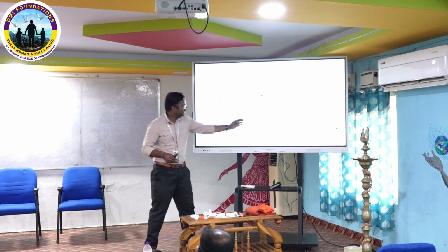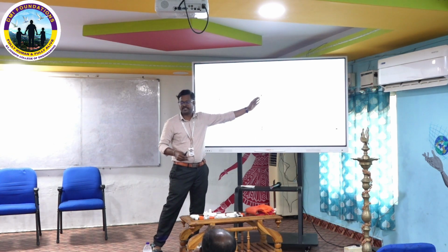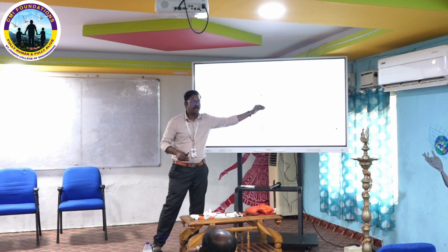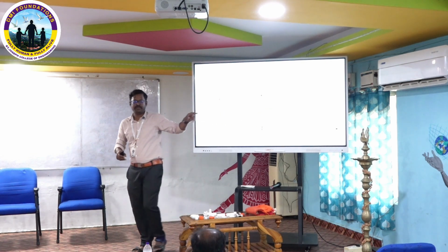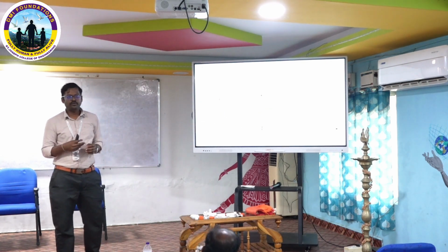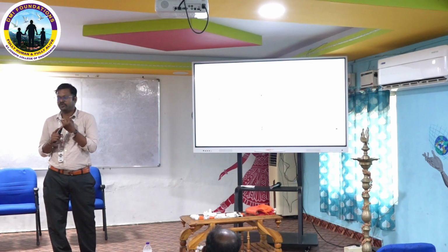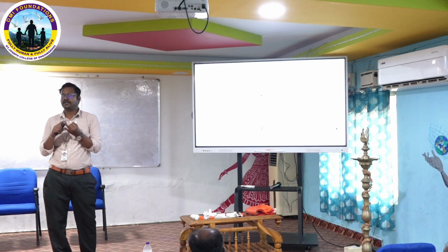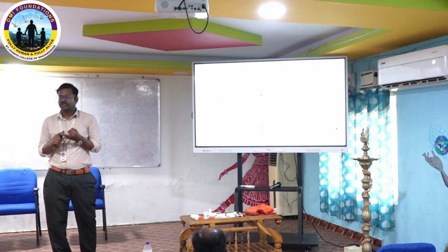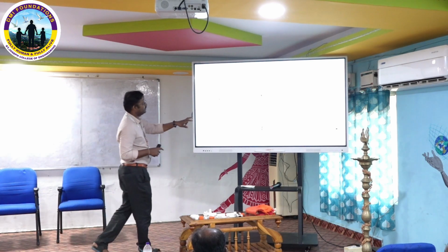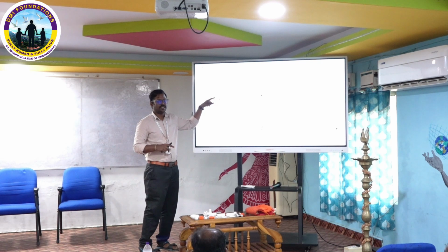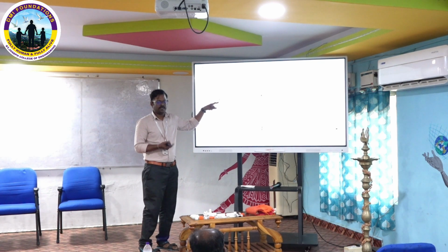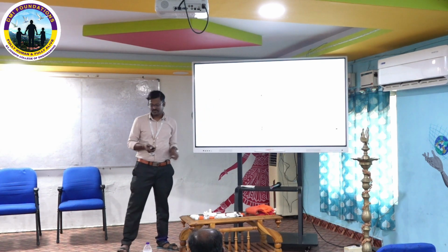So what will happen? It has more compression strength, which means stiffness. Then after that it comes down and deforms in a wavelike manner, with wavelengths. So even though it gives more stiffness and strength, it does not give more energy absorption. So both structures are best for their own reasons. The first one is for energy absorption, the other one is for higher strength and stiffness.